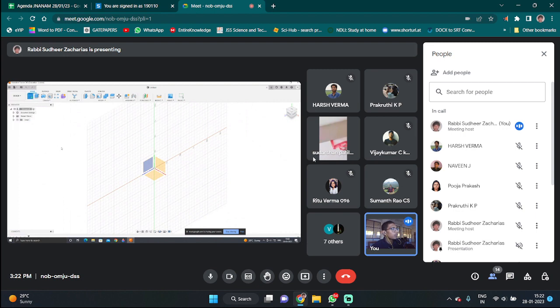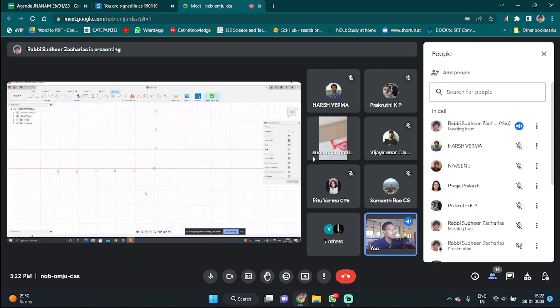So now that we want to start our 3D object, we need to draw the 2D structure first. So let's just select a plane, and then it auto aligns to that plane. And now you can choose the rectangle option here. On the top toolbar we get the sketch option, where you can just draw structure of your choice.